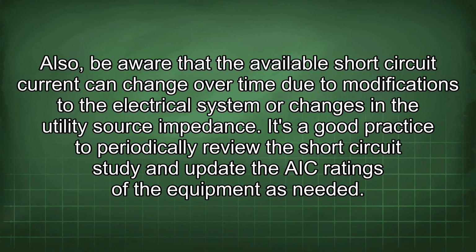Also, be aware that the available short circuit current can change over time due to modifications to the electrical system or changes in the utility source impedance. It's a good practice to periodically review the short circuit study and update the AIC ratings of the equipment as needed.